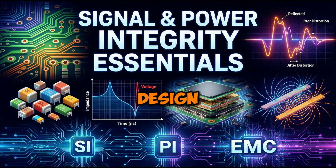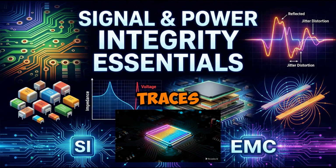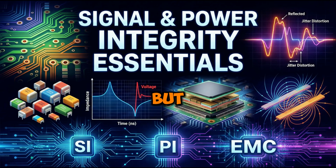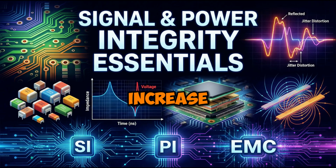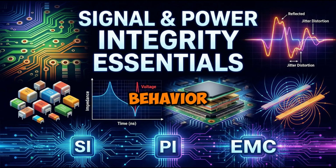Modern digital design looks simple on the surface. We draw schematics, route traces, and expect signals to behave like ideal ones and zeros. But at high speed, signals don't behave like symbols. They behave like electromagnetic waves. As clock frequencies increase and rise times get shorter, the physical design of interconnects starts to dominate system behavior.